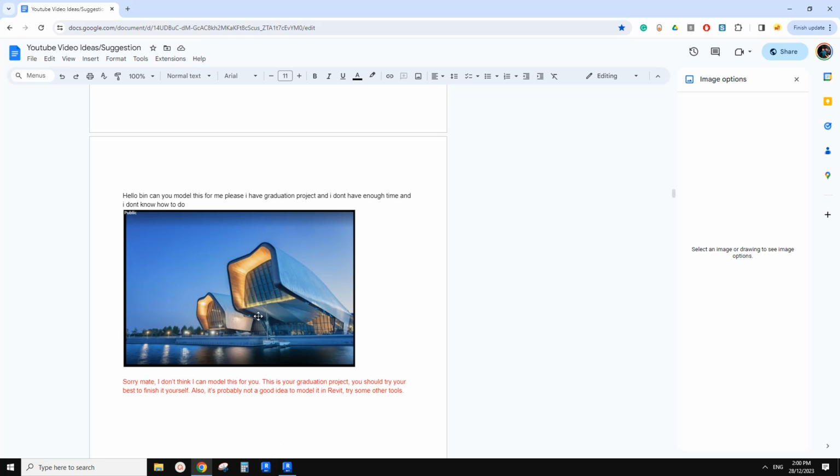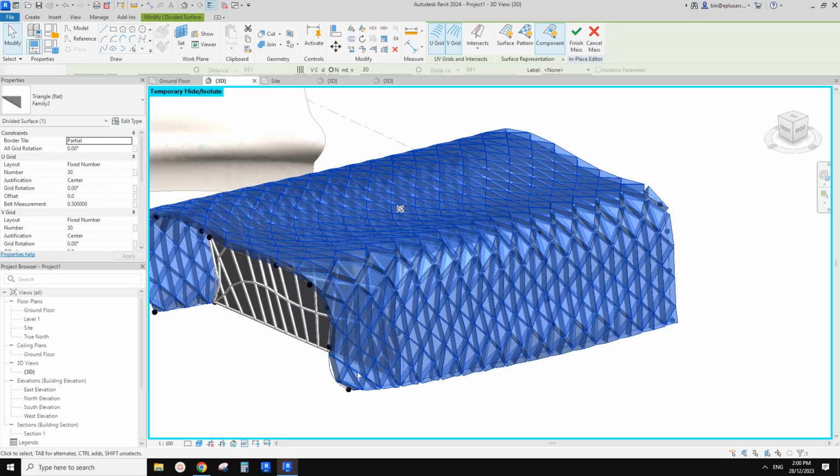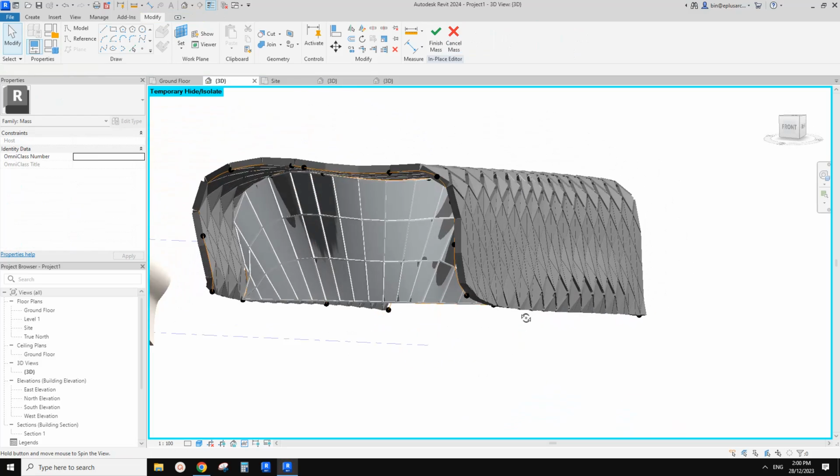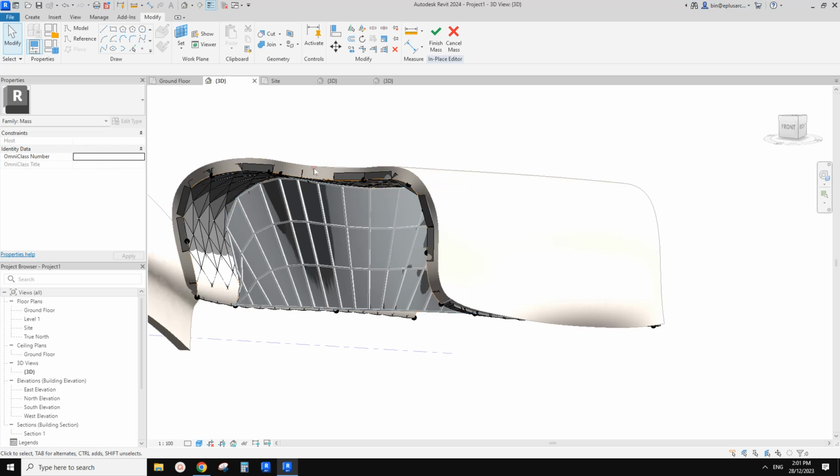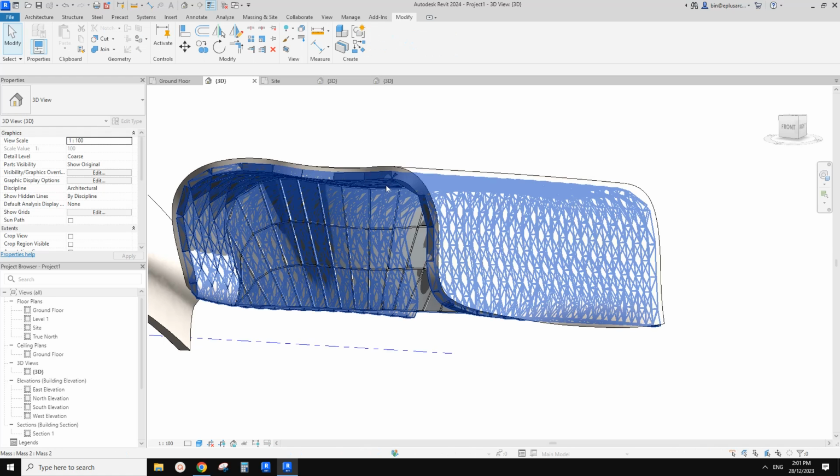So in this scenario, I think maybe it's easier to just place that wall internally. So let's go to here. Oh, quite nice, right? HR, select that wall. So we need to finish the mass first. I probably just created this one too small, so 300 looks very thick, like 1 meter or something.